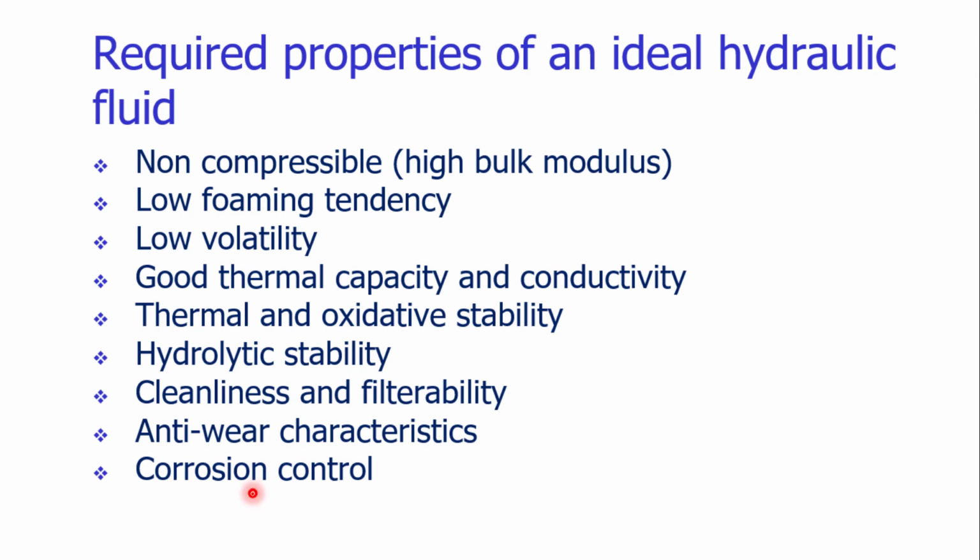It should be non-corrosive. Generally, the hydraulic fluids are corroding the mechanical elements, the ferrous elements of the system, and we need to continuously monitor the condition of the hydraulic elements. Due to the corrosion, the system strength will get reduced and that may lead to the failure of the system. The corrosion is a concern in the hydraulic fluid based systems. The hydraulic fluid should provide minimum possible corrosion inside the system.